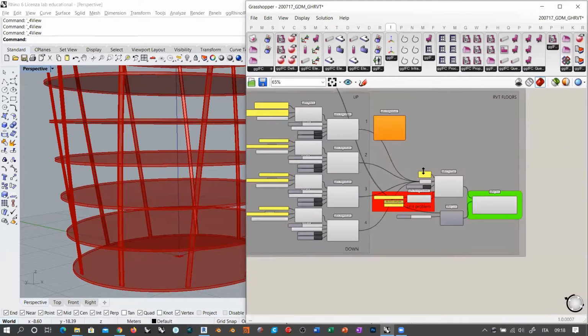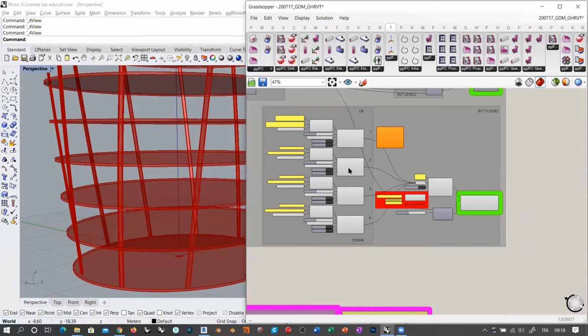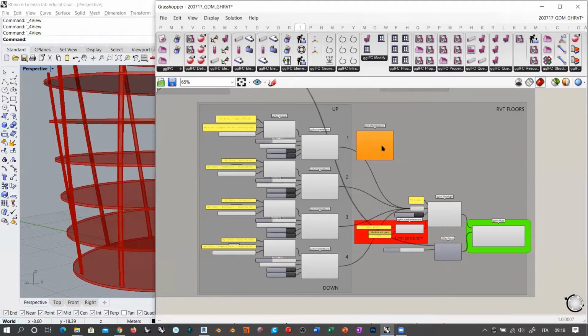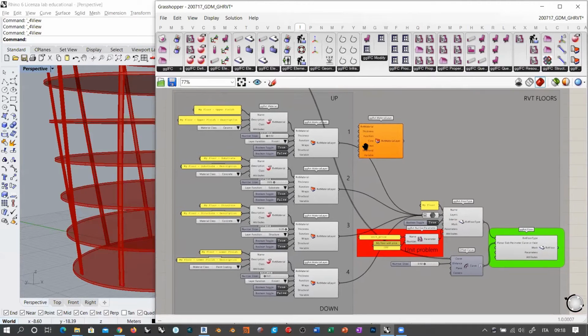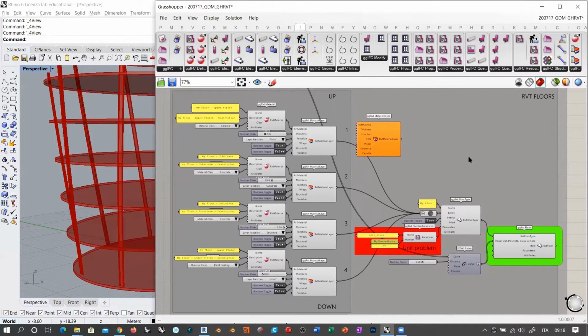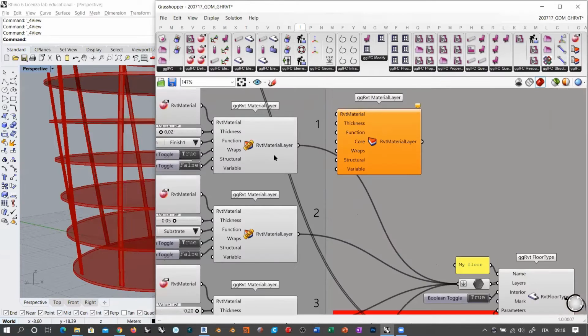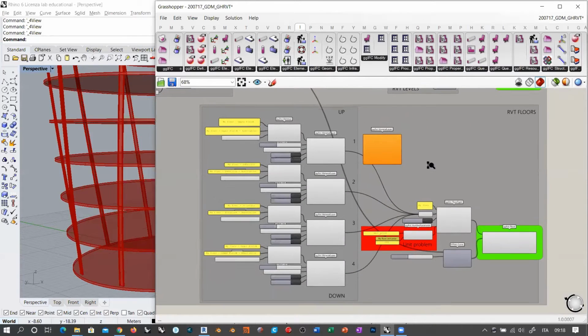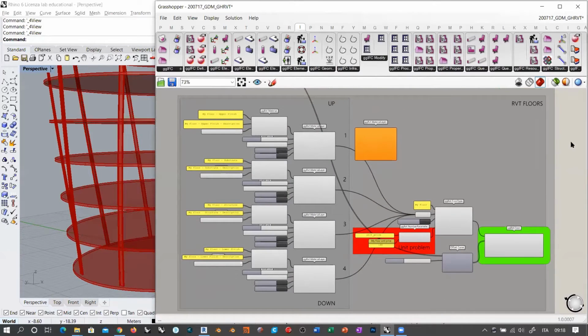I'm going to quickly go through this new material layer. So nice to be part of the development of these tools. Basically we must substitute this old material layer with a new one. I do recommend that you install the new version of the Rhino 6 IFC exporter.